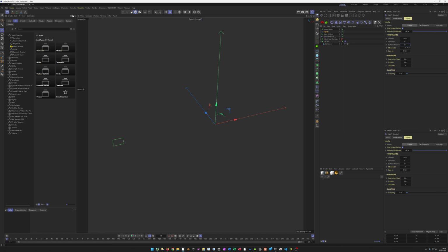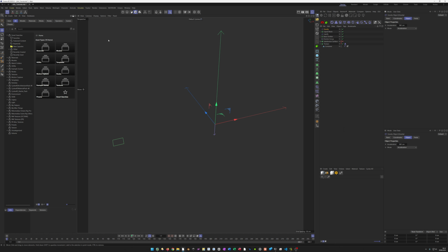So let's go back and bring in the simulate forces. Here we have a gravity as well. And with this gravity, you see this arrow here? I can say in which direction the gravity runs. So when I now take the gravity and drag it a little to the side here, the fluid thinks it goes downhill, and that should fill this whole thing much quicker.